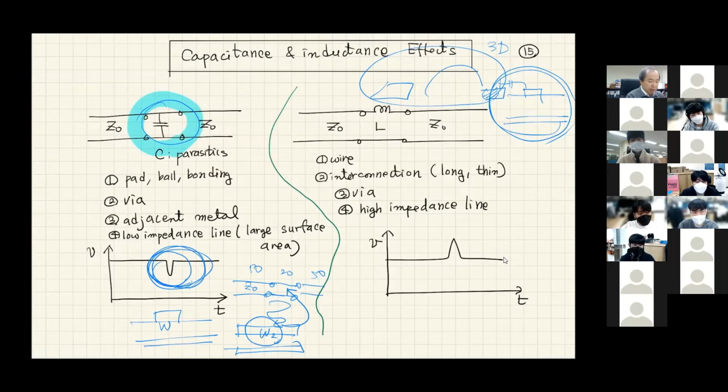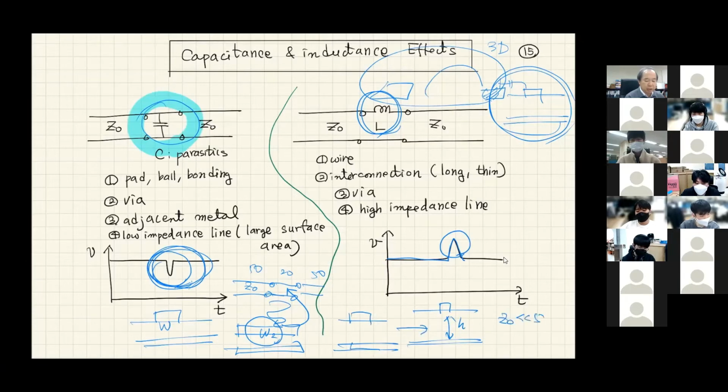However, if you have a case where you have very inductive element, usually you're gonna see these higher ripples. And this kind of thing can happen when you have transmission line which has very high thickness compared to 50 ohm, this can cause characteristic impedance smaller than 50 ohm. Then you're gonna observe this kind of positive pulse while you are sending high-speed digital signal.